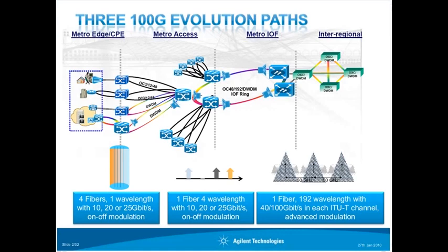I saw solutions like of course WDM systems where you just transmit over 4 wavelengths which are very far away from each other. The shorter the reach, the less important the fiber becomes. So people are just taking 4 fibers instead of multiplexing it to one single fiber.